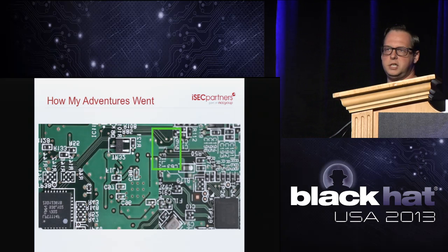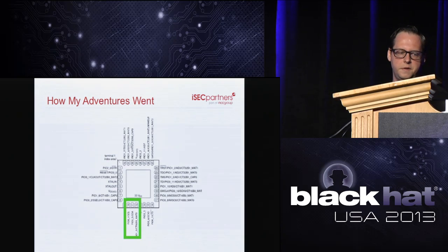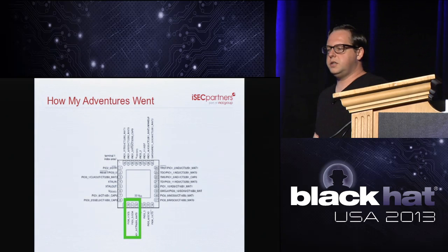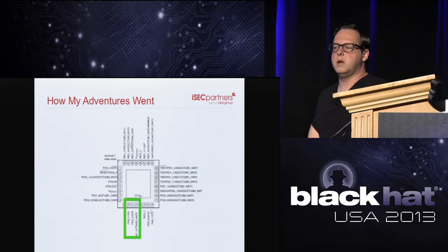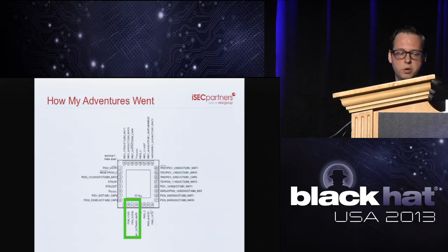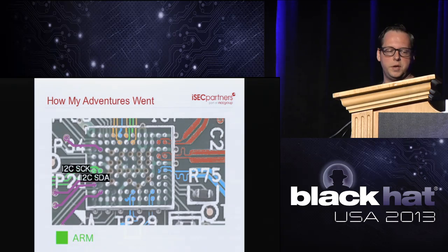So now that we have data sheets for our ARM, let's go ahead and figure out what these are. Looks like 2 of them are I2C. For those who are not familiar, I2C is a bus for 2 chips communicating with each other. So it looks like the ARM and the Thunderbolt controller are communicating via I2C. We can add those 2 pins to our pinout for Thunderbolt.